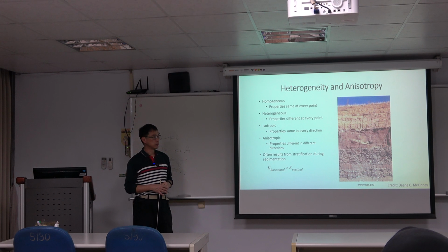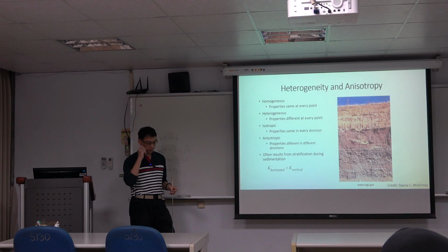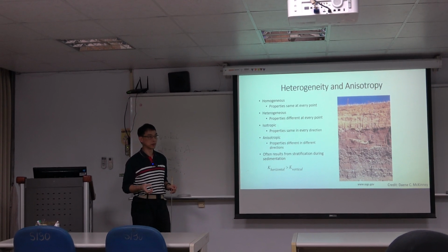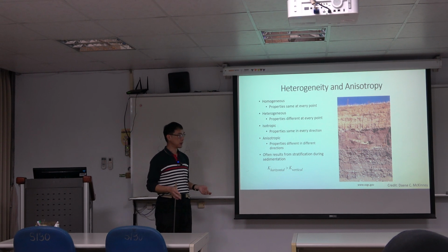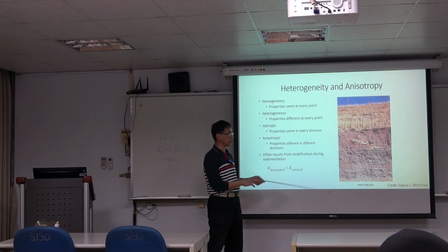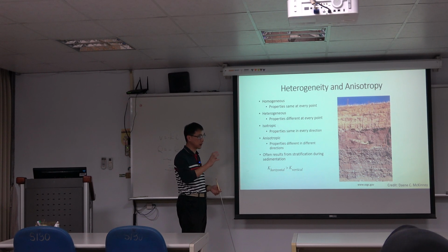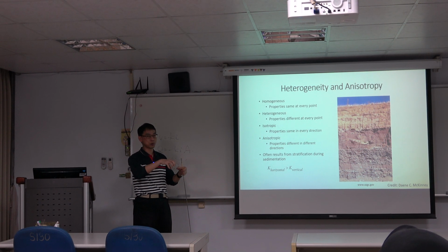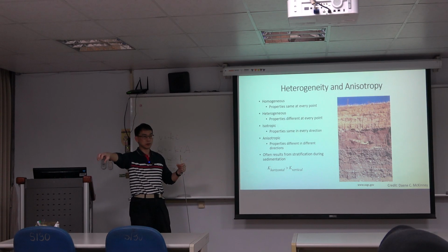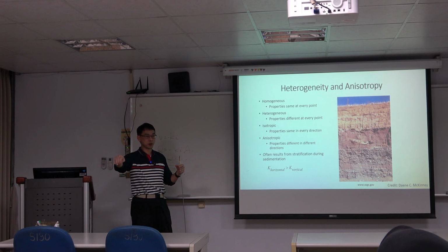Okay. So one of the concepts is that when the hydraulic properties are within 1 order of magnitude, commonly we will say that they are similar, although they can have several times differences. But if they are in the same order, we will say they are similar because they have larger uncertainties. Even using the same material to do the experiments, they can have larger variations. If they are close, maybe the property is quite similar. But when you have a longer distance, it will change because the deposit environment will change.